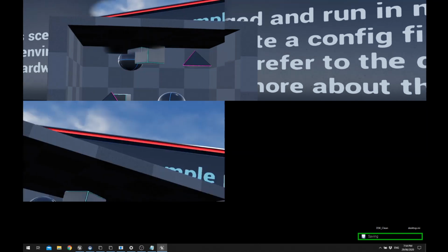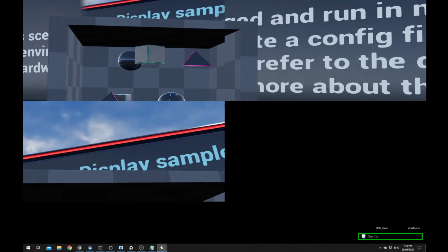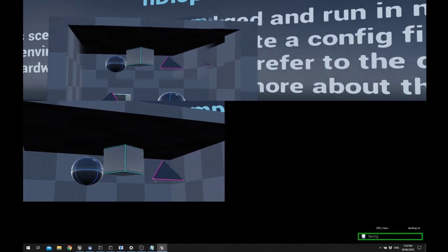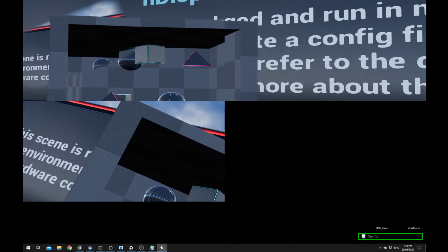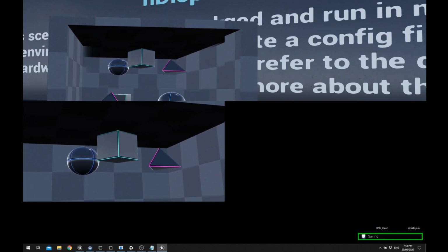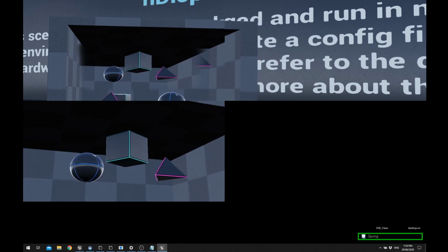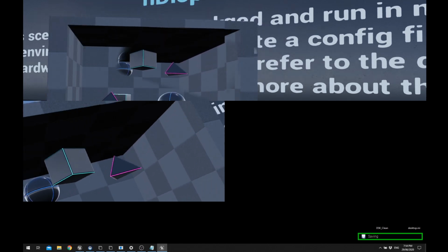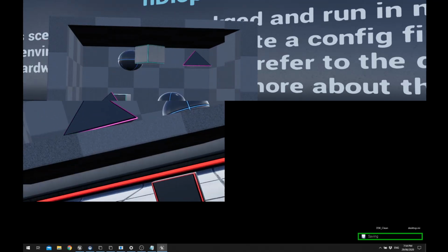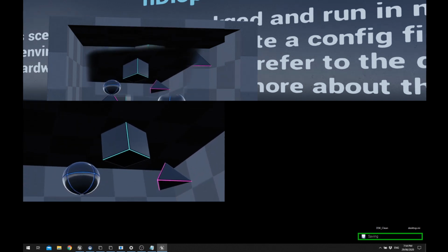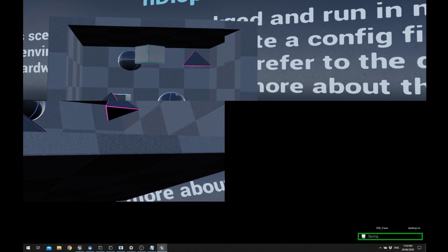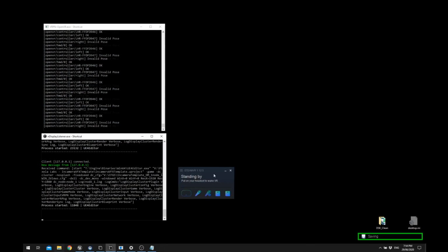One thing I will actually point out is for any key commands to actually work within this window, you need to have focus to it. And oftentimes when you boot up an nDisplay thing, it will show up on the monitor and look like it's fine and you can get this projection working, but none of your keys work because it's not actually the foreground app. So often you have to tab to it if you've gone in through having other apps open or clicked on. There's potentially a really simple and easy way to make sure that is always the focused app that I don't know about. But just be aware that that's the thing. Sometimes you're thinking you're not being able to get input and things aren't working, when they are, you're just not talking to that app. So I'll escape out of that.